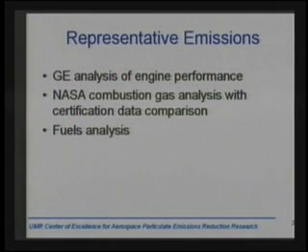First of all, there are no standard PM measurements. There's not a certification standard for PM other than smoke number. And that's not a fundamental measurement of particulate matter. It just tells you how dirty a filter paper gets if a known volume of exhaust has passed through it. And that can be meaningful.